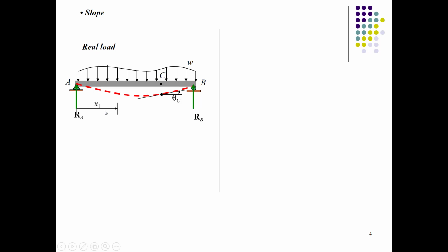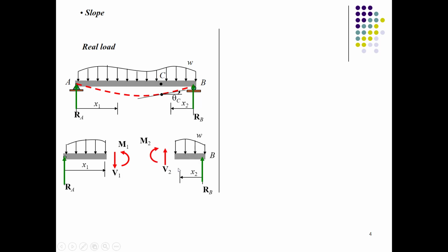You can see there is only one section over here because it's a distributed load, and the nature of the load does not change, so it is adequate to take one section. So you have internal forces of shear v1 and m1, and you can also take the section after the application of C, after the C point.